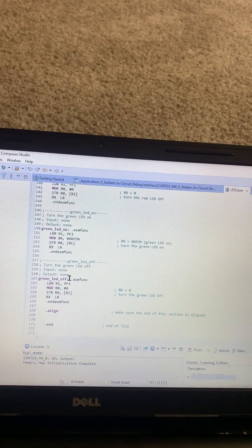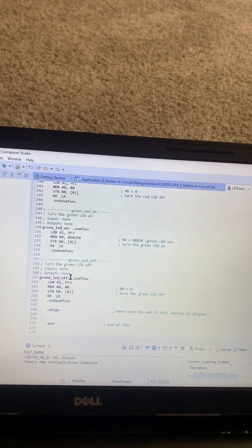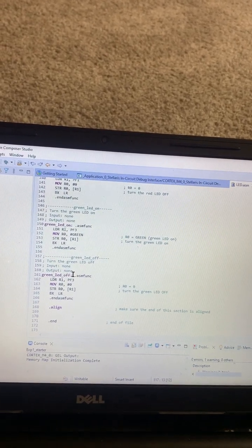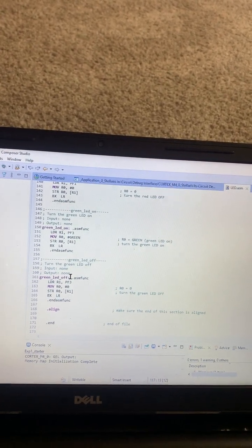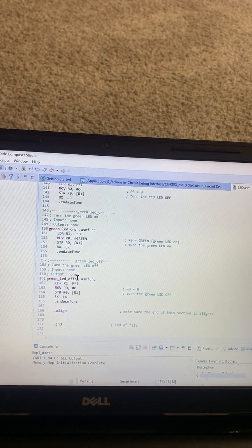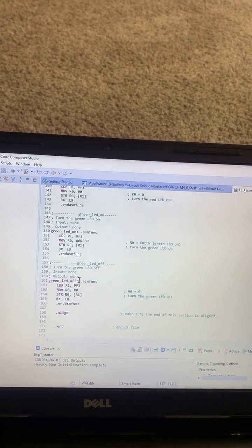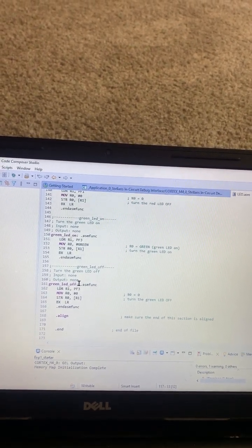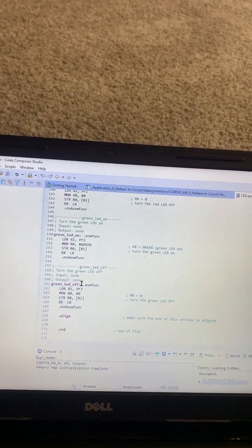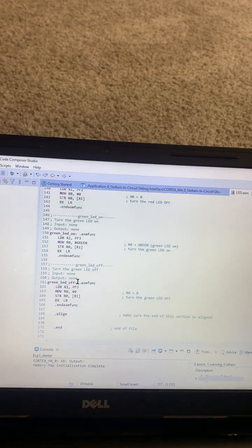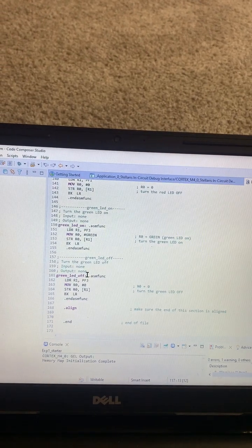It defines some constants to represent the colors of the LEDs like red, blue, and green, and the switches on the board such as SW1 and SW2, and the memory address of the SYSCTL_RCGC_GPIO_R register, which is used to activate the clock of port F.